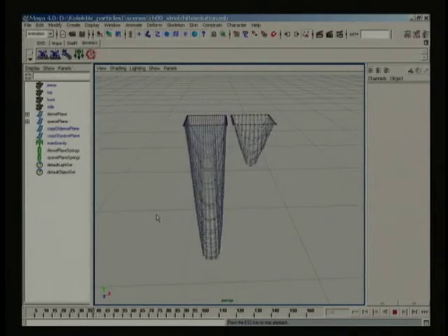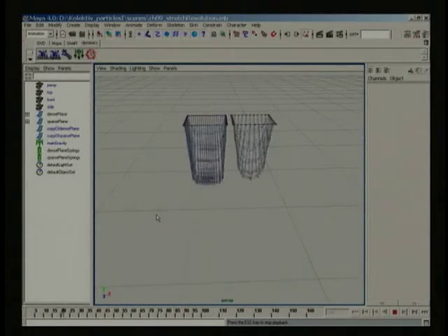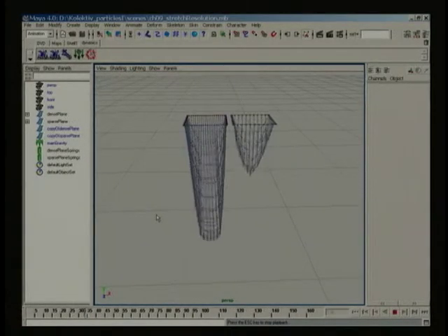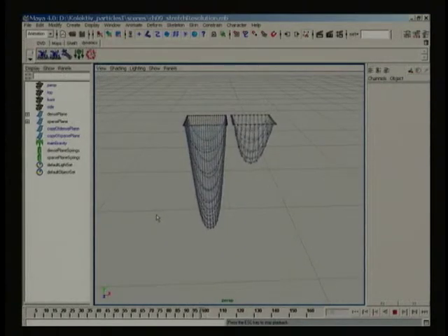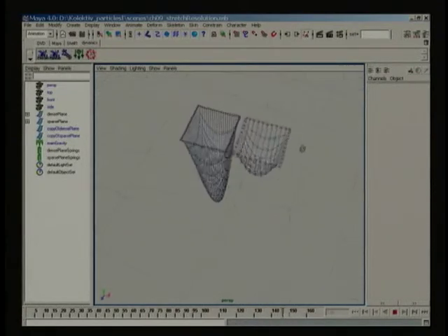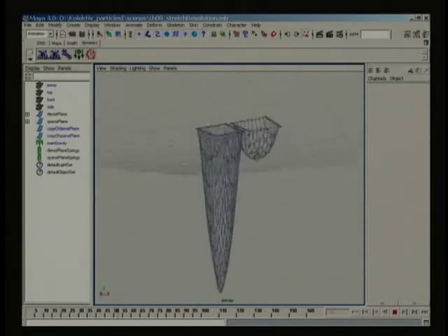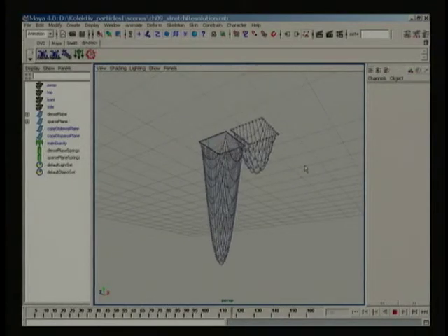You could theoretically increase the stiffness of the springs on the high-resolution grid, add additional spring objects, or increase goal weight to achieve less stretching, but applying springs to lower-resolution objects usually results in better simulations. With lower-resolution softbodies, you have less overhead due to the smaller number of particles and springs required to solve the simulation. If you are creating a flag, curtains, or any type of fabric sheet, more points in your surface results in more stretching, as well as the increased chance of unwanted interpenetration.